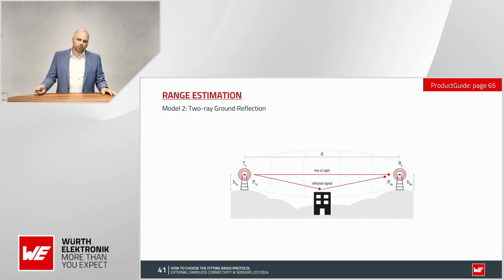In reality, you always have reflected signals, and things and walls and trees and a lot of other things in the range of the radio signal. Even if you have a direct line of sight, so that a direct connection is possible, you have to keep in mind that the electromagnetic wave does not form a line but a shape, so it always depends on the environment.